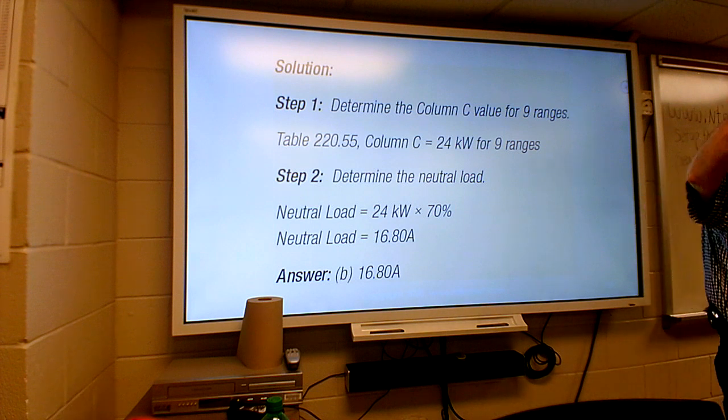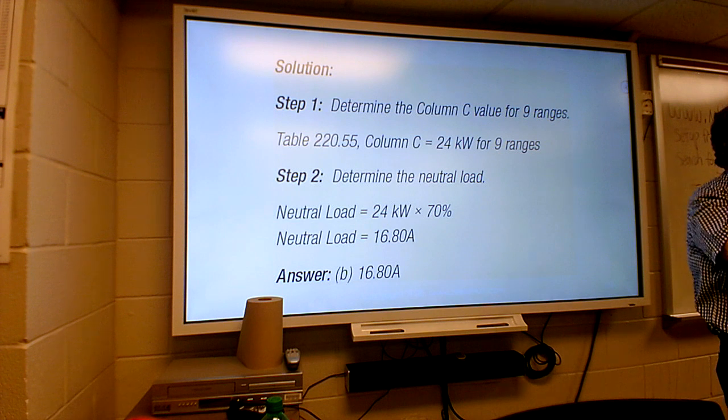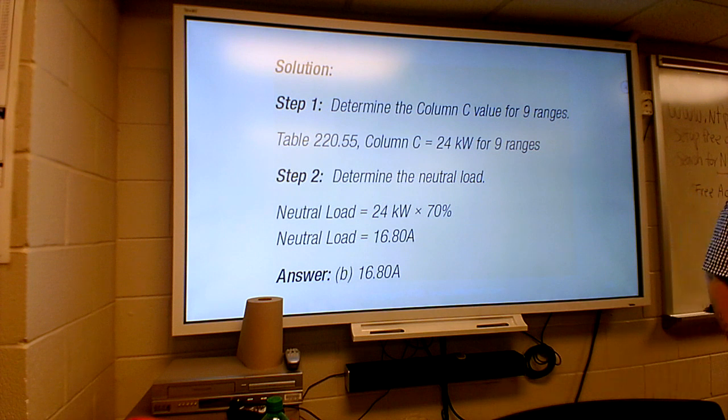Everybody got your table in front of you, 220.55. Okay, so you're in column C because it's 12 kilowatt, and there's 9 of them. So what is our demand factor? 24.